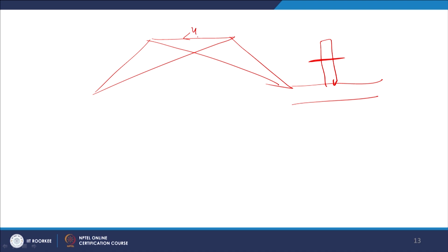In this velocity diagram, we have u, V1 and VR1, and this is the blade inlet angle. The nozzle inlet angle is fixed, and V1 is fixed. Now, beta 1 will change according to u, and u is not fixed because u is equal to pi d n by 60.